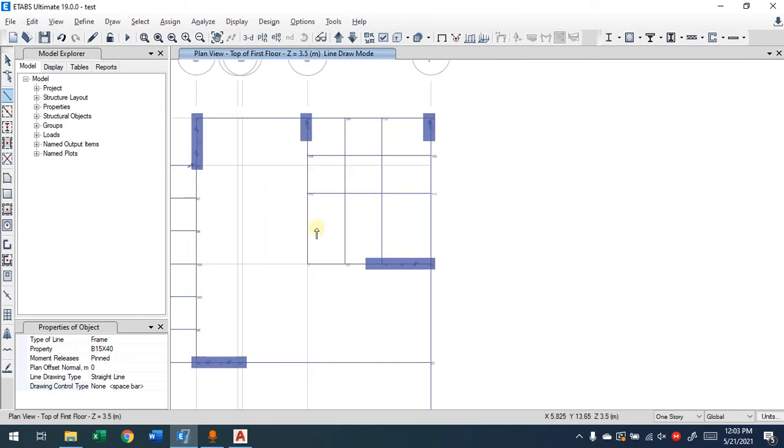Like this way I provide the things for myself here. So if I want to provide one here, I can do it as well, but I didn't provide a reference point. There are two ways to do it, whether to use the dynamic dimensions, or provide a reference point for myself. So let's say I want to provide one here at 70. I can click, and when I see it's green, so it's horizontal, I can click the other one, right click, and I have this system provided.